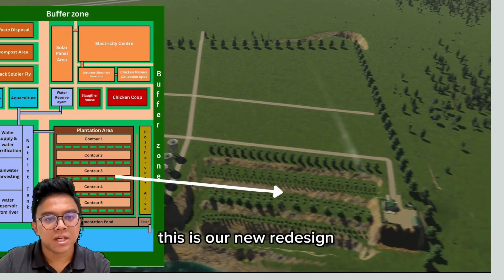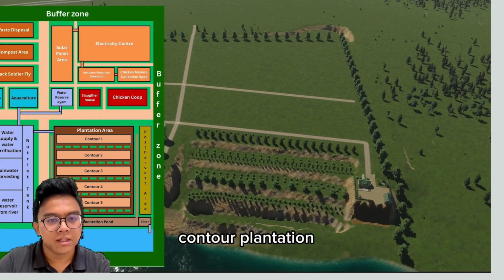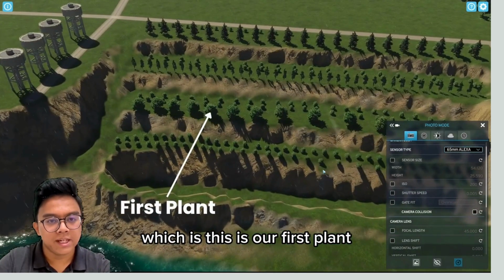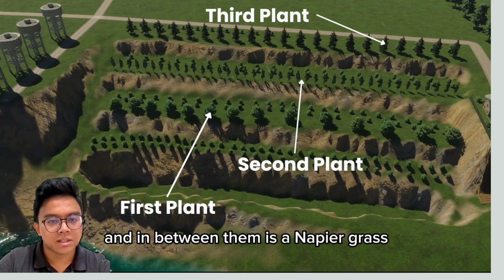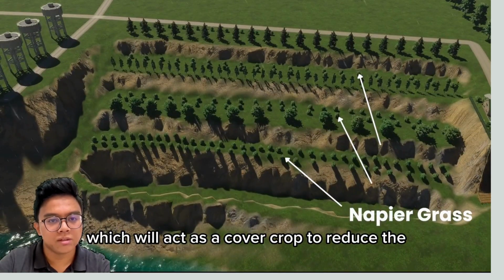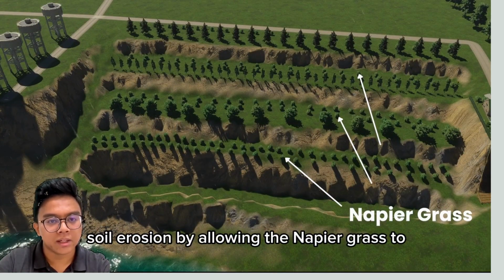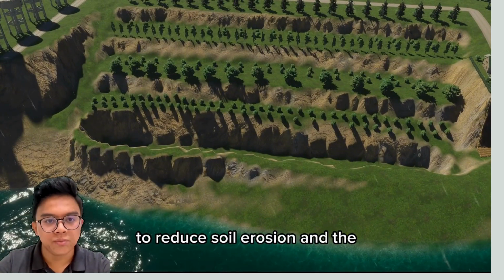This is our new redesign, which we designed with terraced contour plantation, where this is our first plan, that is our second plan, and that is our third plan. And in between them is napier grass, which will act as a cover crop to reduce soil erosion by allowing the napier grass roots to grab onto the soil.